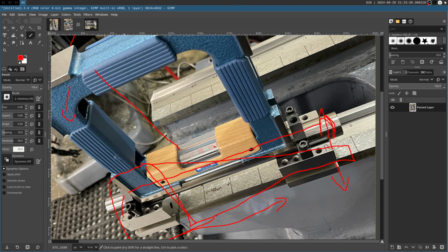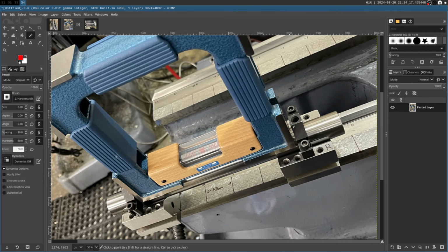And I've been able to rub the dumbbell on the surface plate to pick up the marking of where the dumbbell makes contact with the surface plate, to guarantee that I know that the 2 planes of the bottom surface of the 2 V blocks are in the exact same plane. Right? So I know that the bottom of this is perfectly flat. I know that the bar on my surface plate doesn't indicate more than like 1 micron of deviation across the entire spot, which also means that it's parallel. But the parallelism doesn't matter anyways. That's kind of all of the measurements there.